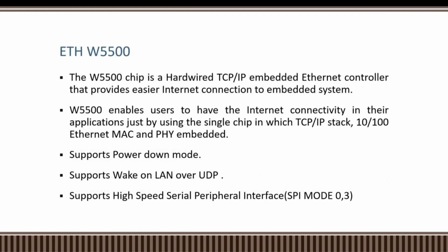Ethernet, ETH-W5500. The W5500 chip is a hardwired TCP/IP embedded Ethernet controller that provides easier internet connection to embedded systems. Here TCP stands for Transmission Control Protocol and IP stands for Internet Protocol. It enables users to have internet connectivity in their applications just by using a single chip in which the TCP/IP stack, 10/100 Ethernet MAC and PHY are embedded.